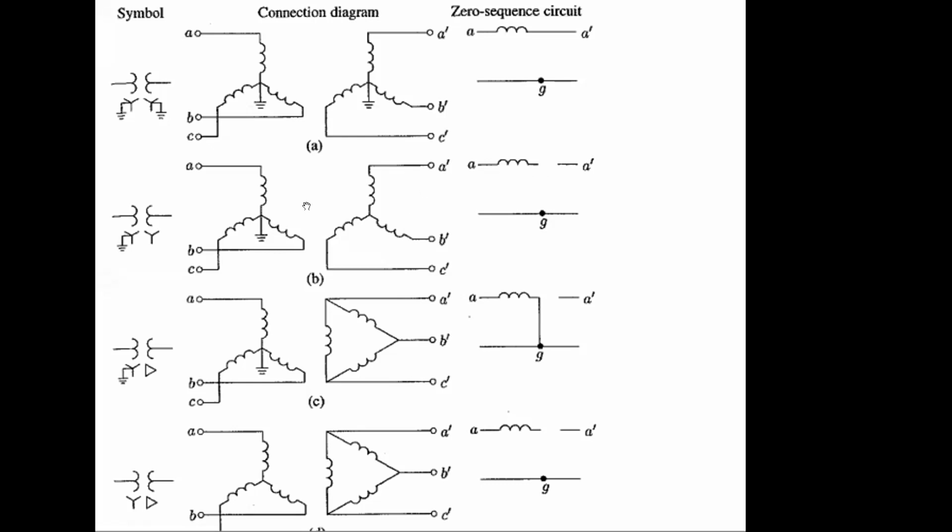Why? No, sir. Here you can see the actual transformer symbol. Which part has ground, primary or secondary? Secondary. Secondary has open, right? So secondary open, that means this path on the secondary side should be open.